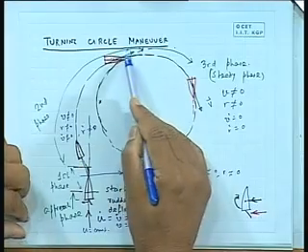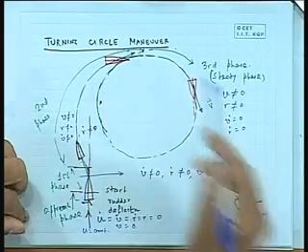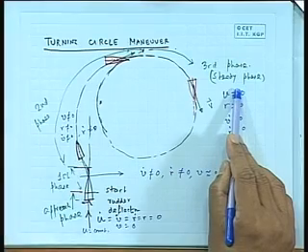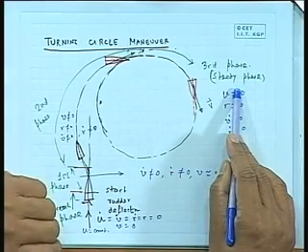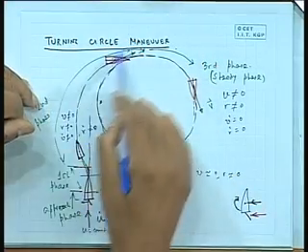Newton's equation says that mass into acceleration is force. If my ship is moving at 10 meters per second, it is not changing, it is not having acceleration, which means there is no net X force. So if the speed is steady at 10, that means there is no acceleration. That is what is happening. So eventually this vessel will reach a steady turn, it will keep on turning steadily, which means it has only velocities but no acceleration. It has reached a sway velocity of some meters per second and a yaw velocity of some degrees per second. It will keep on doing that. So this is what we call my final phase.